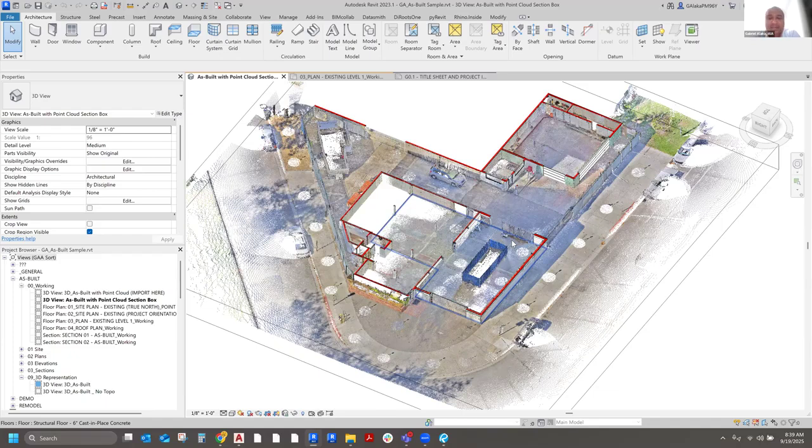So by the time that the project is done, the actual building would no longer look exactly like the actual plans from like several years ago. So even on a contractor's side, at the very end, some big projects require the contractor to submit as-built drawings. So at the very end, and this is most likely with the use of point clouds, a lot of contractors will go around, scan the entire building and then create new drawings to give to the client of the as-built conditions.